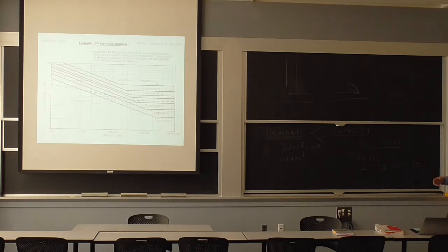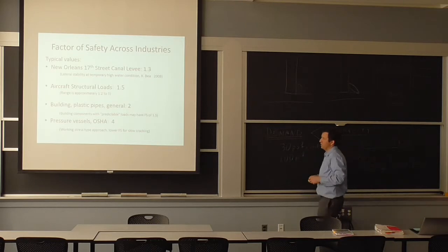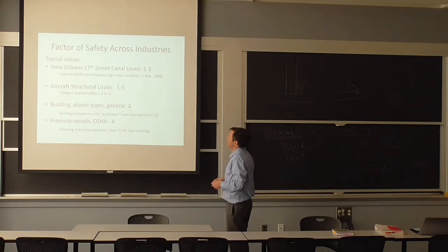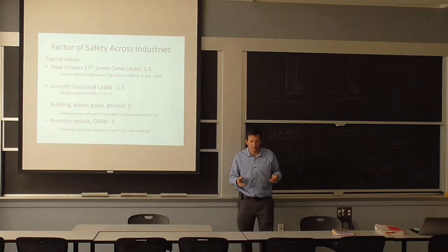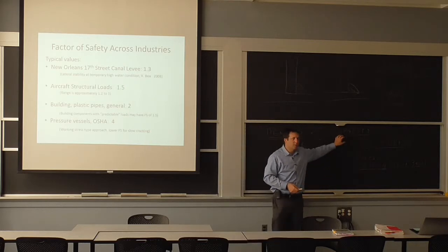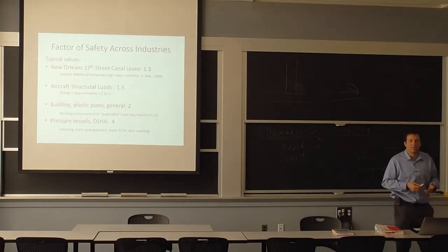Now, this is very general, and what I want to say is how exactly you do this calculation depends on the industry. If you're doing something in the civil engineering world, lots of times they don't trust the soil very much because they had some bad experience with it. Over time, the soil just tends to move. So when they go to the capacity, they put very, very low properties on the resistance of the soil, just kind of saying it's very viscous and it really won't hold itself very much.